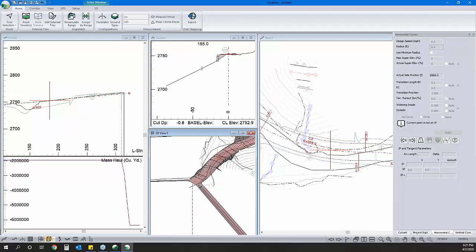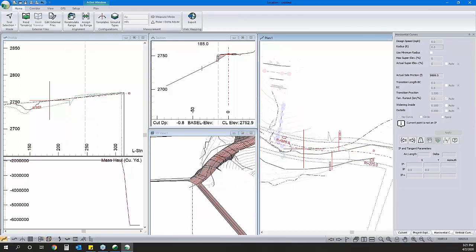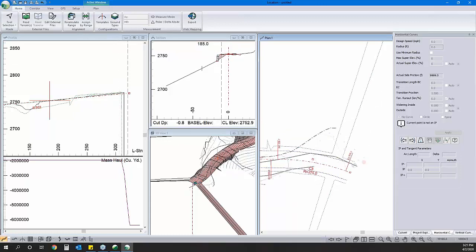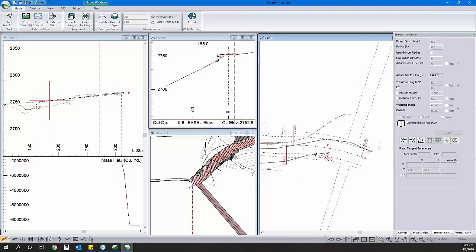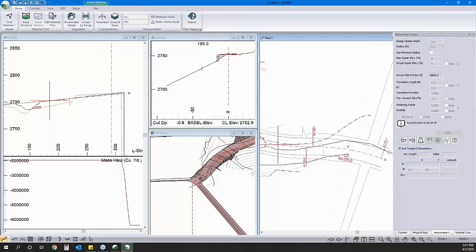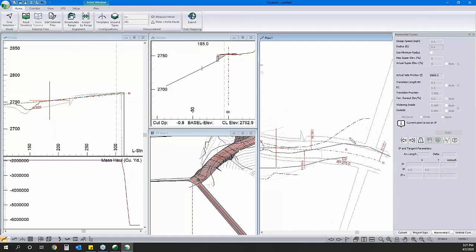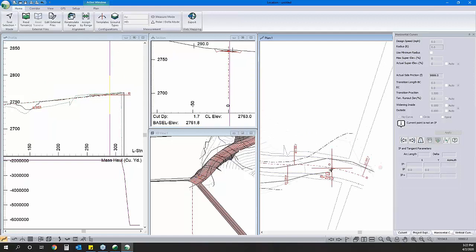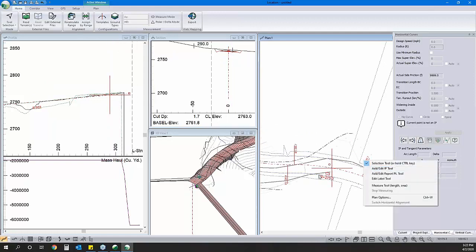Now these runaway fills, in previous webinars, I've mentioned that the bridge template is nice for things other than just bridges. The reason for that is it's an empty template, so you can make it so we aren't calculating cuts and fills in areas beyond the design.